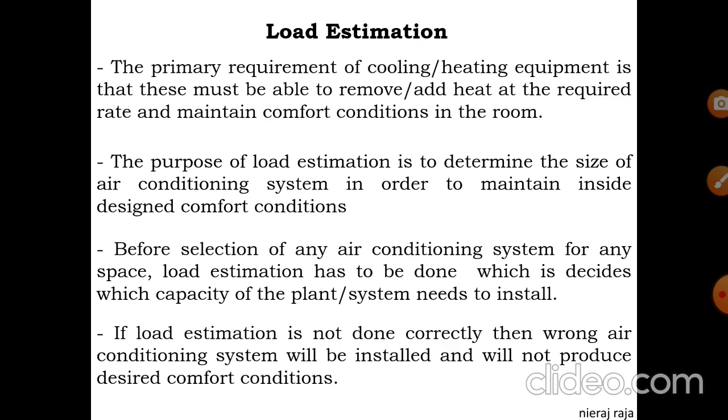This is the most important, as I said: if the load estimation is not done properly, it is an essential step. Whenever you purchase or install any air conditioning system, the HVAC engineer or design engineer first does the load estimation, because this ensures which system he needs to purchase and install. If the load estimation is wrong, you will install the wrong or an inappropriate air conditioning system, and it will not give you the desired comfort conditions.